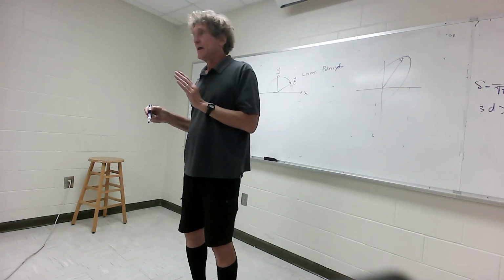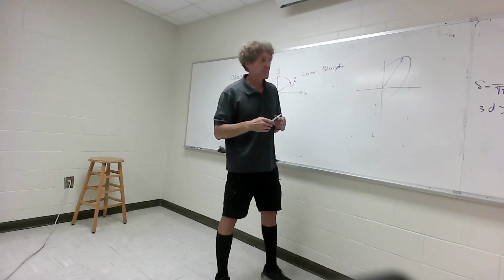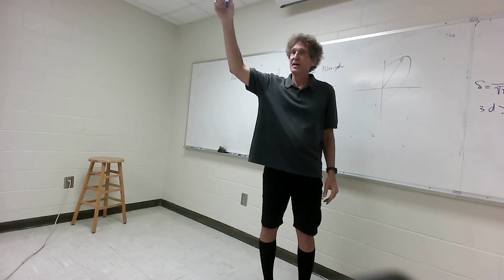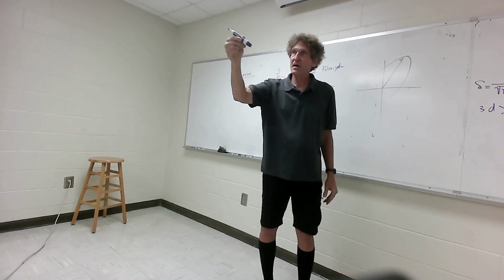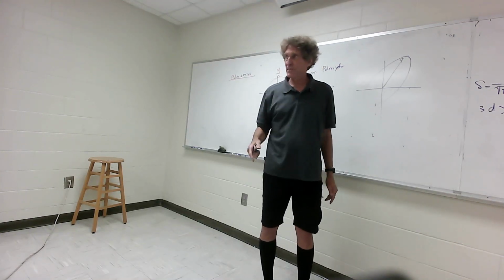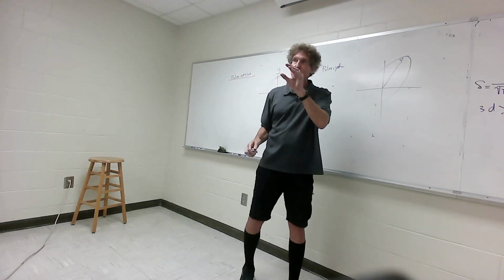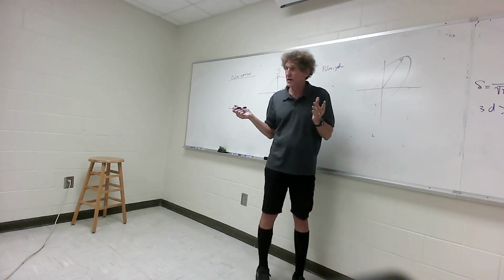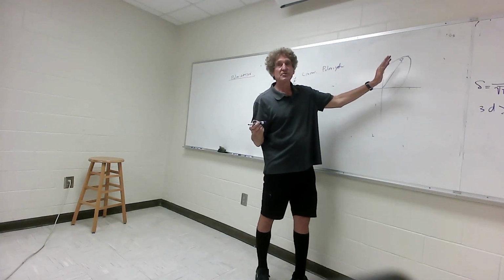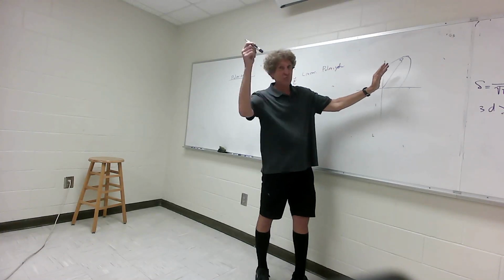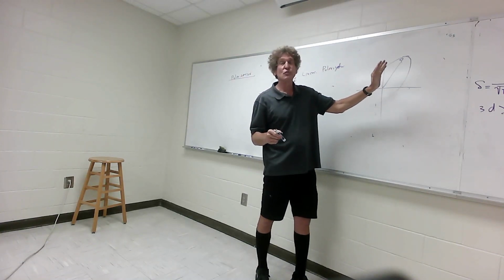Y'all follow me? Now, elliptical polarization has its place because, as raindrops fall, and I'm not going to pretend to know everything about this, in a velocity field they may be going sideways. Raindrops are teardrops. They're approximately elliptical, not quite, and usually conducting. So if I have a weather radar with an elliptically polarized, or even linear polarized, signal, and I look at the orientation I'm transmitting where I get the maximum amount of signal back from a given thunderstorm area, then I know that's probably the orientation of the actual rain.